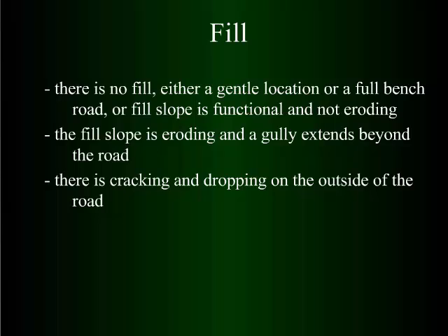The other thing is that maybe you have a cross drain pipe, like you saw before, where it's eroding down below it and starts cutting the toe of the slope. A lot of times your pipe will stick out to here and the water plunges out and starts eroding the toe of this slope, and pretty quick it cuts it back, and then this whole fill wants to start moving down the hill because the support's been removed.